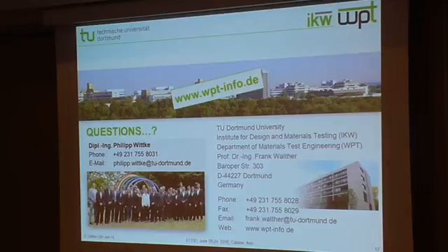Is there any like heat affected areas, or do you have to do any stress relief, or is that going to be further research from the friction drilling? So at first, I've not shown some microstructural changes during the friction drilling, because this is very important for us to investigate, of course, work hardening effects and stuff. So we will have to correlate this with microstructure and micro hardness along the threads. So is this going in this direction? Yeah.